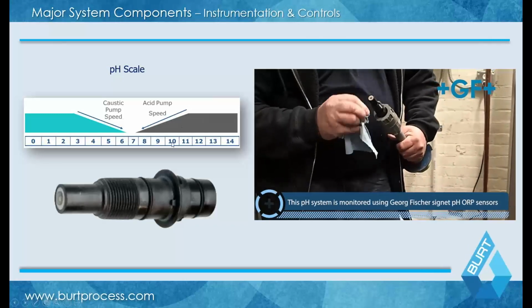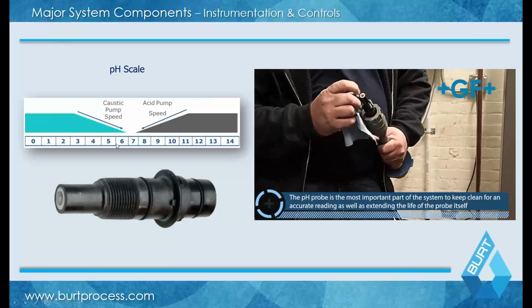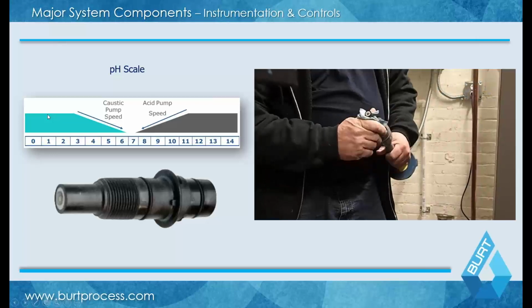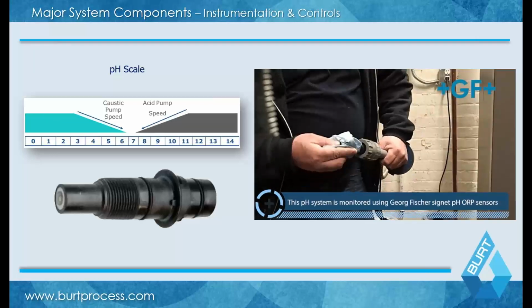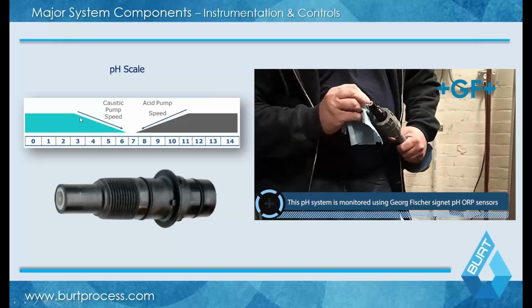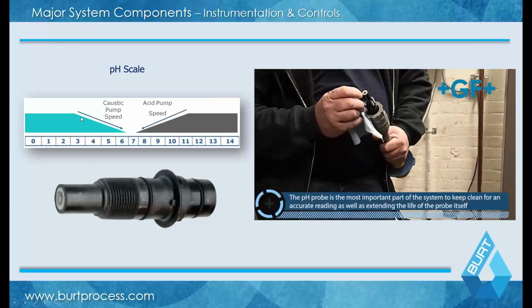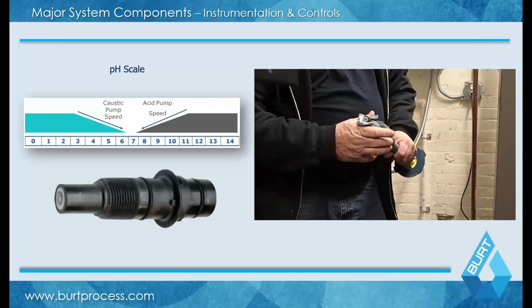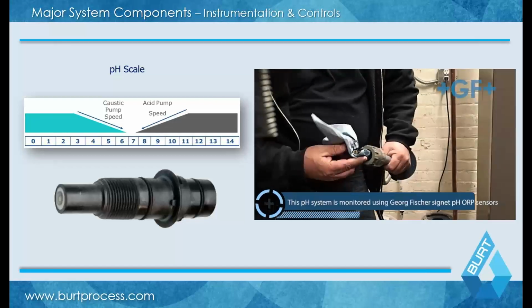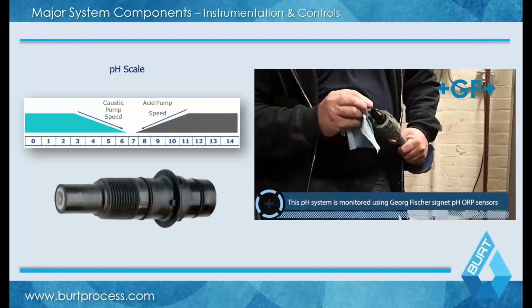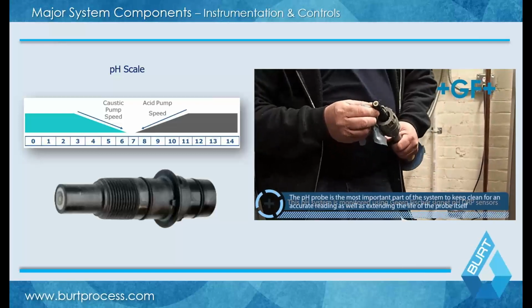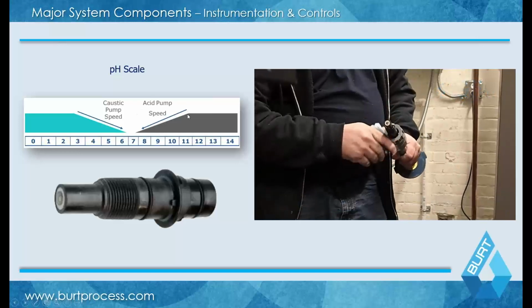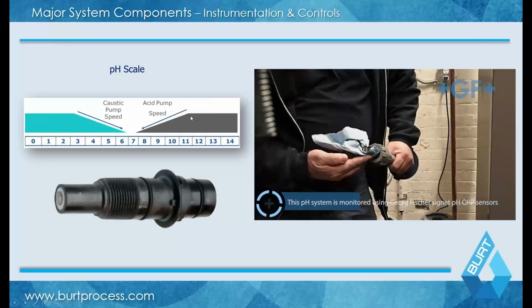This is the pH scale we talked about earlier, from 0 to 14. When you're out here in the more extreme waste ranges, you can basically run your metering pumps at a fairly high flow rate. As you move closer and closer to neutral, your metering pumps need to turn down proportional to the pH scale. So within your treatment tank, you have a pH probe, you're monitoring the pH. As you get closer to 7, say around 3, you're going to start to turn it down 10, 100, 1,000 to 1 to effectively match that pH scale. And this goes in both the acid as well as the caustic direction, which is why almost all pH systems are two-way adjustments.